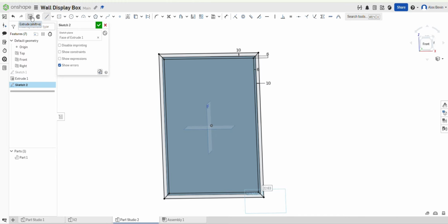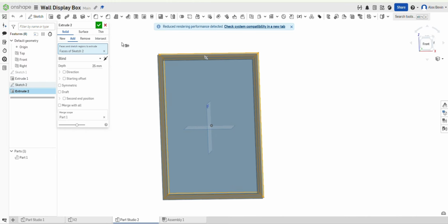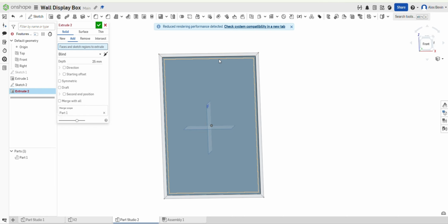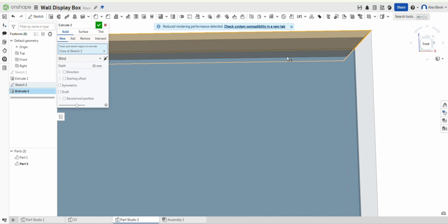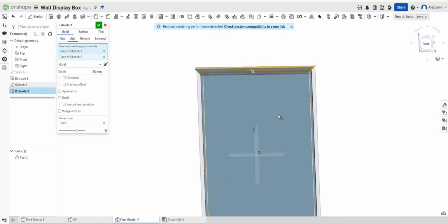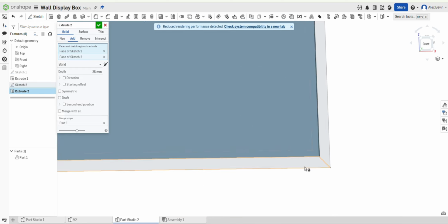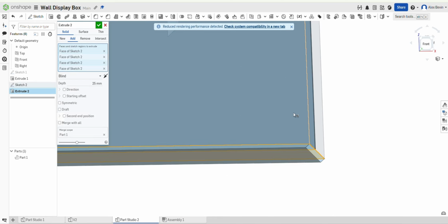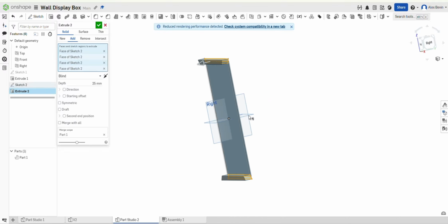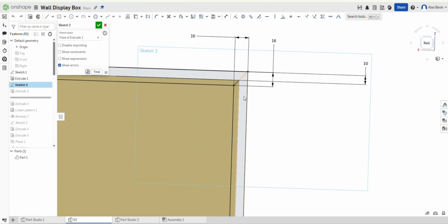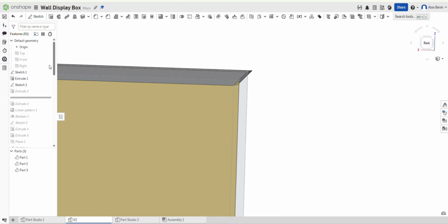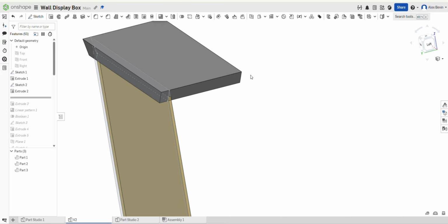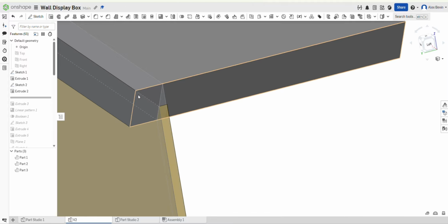Part 6. Extrude the first timber blocks as new parts, top plus bottom. Now I click Extrude. Important, I'm not extruding the whole face. I'm selecting only the regions that represent the top and bottom blocks. Now for the depth, the timber block total depth is 100mm. We're going to build it using two key values, 10mm in one direction and 90mm in the other direction, so the total depth ends up at 100. Before I press OK, this is